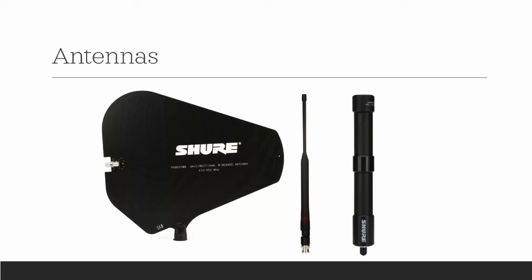The last point that I want to make in terms of antennas and the signal is that RF signals are polarized, which means that the transmitter and receiver antennas must be aligned to pick up the signal. So if I've got a transmitter antenna which is straight up and down, and a receiver antenna which is 90 degrees horizontal, so they're perpendicular to each other, they are not polarized-matched, and they will be out of phase with each other.